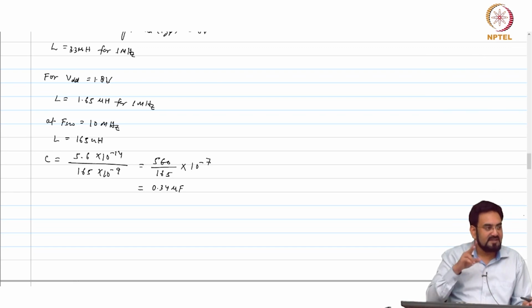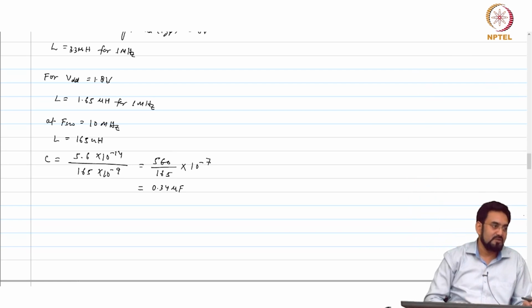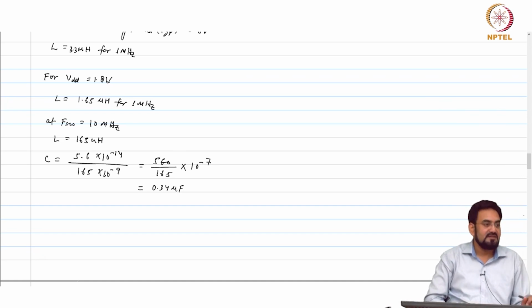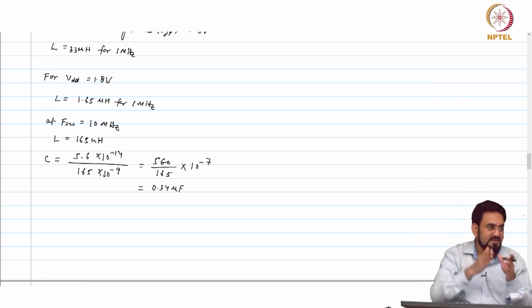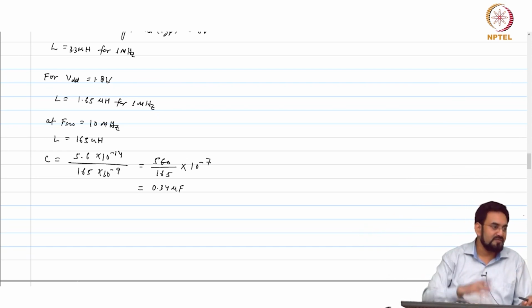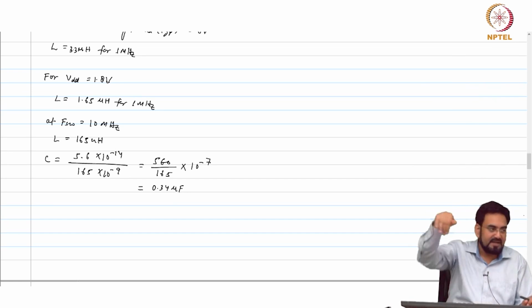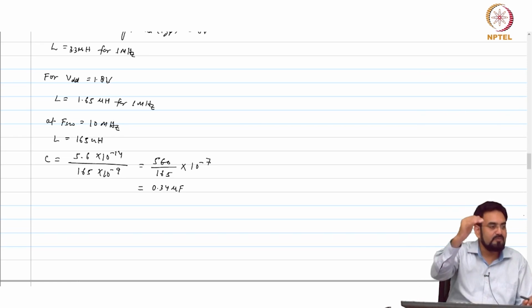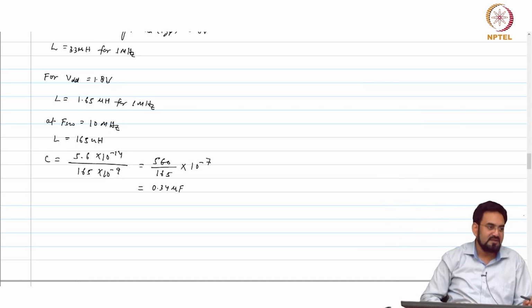So, one is bandwidth limited, but if you are not limited by bandwidth, then you will be limited by inductor current slope. Inductor current slope means you have an instantaneous change in the duty cycle, so whenever your load change happens, you stretch your duty cycle to 100% right away in the next cycle. But that is not true if you are limited by bandwidth. Let us say you have a 0.5 volt control voltage for a 1 volt ramp, when you are operating at around 50% duty cycle. From 0.5 it will not right away go to 1 volt in the next cycle; it will take some time because of the compensator.